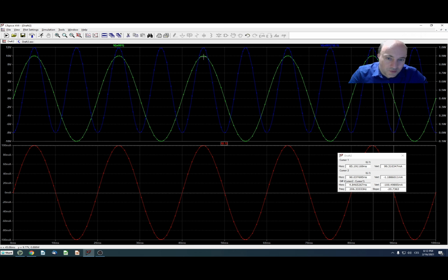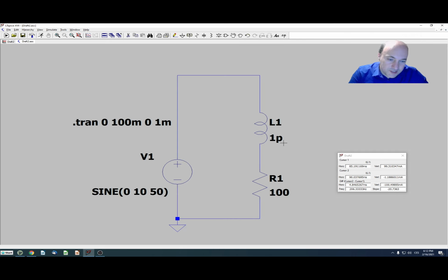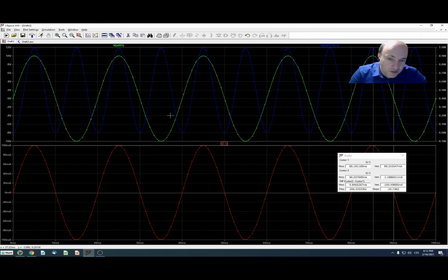Here we're simply multiplying a positive number by a positive number, so we have a positive result, and here we multiply negative voltage with negative current, so we still have a positive power. So for a resistive load, the power is being transferred only from the power supply to my resistor, there is nothing going back, and it's always positive.